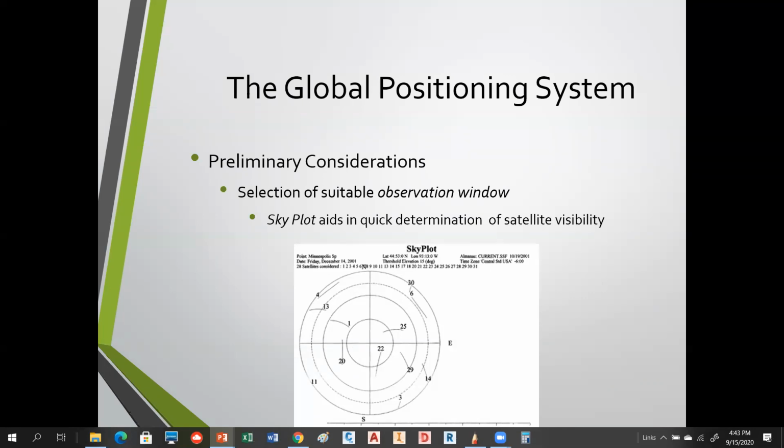The other thing is occasionally, the DoD puts out that certain satellite, like satellite 25, is giving you bad observations. They'll either kick it off, but they may not turn it off for you to use. But you may have to figure out that, like you said, you got a bad satellite or a bad reading. You might get that with GLONASS sometimes, where we don't have that information.